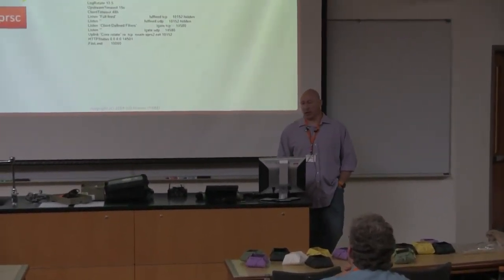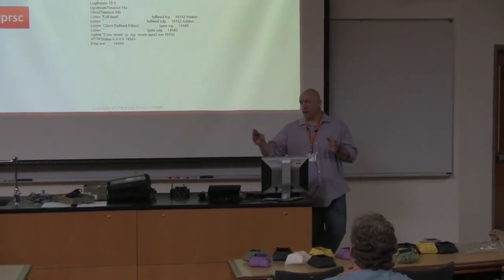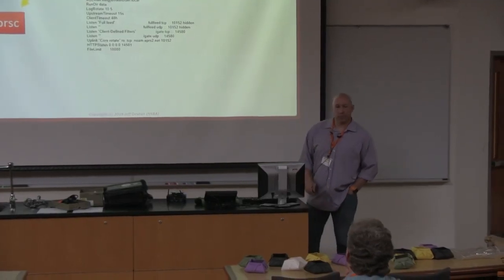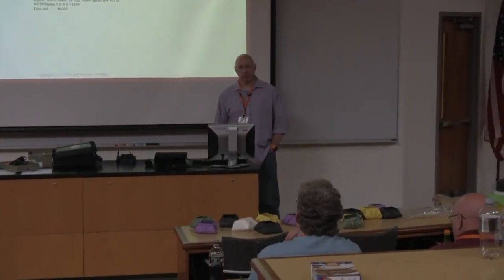Yeah, Jeff's comment, for those online, was that RTL FM will scan those frequencies. It doesn't do it in parallel. You might also point out that Direwolf does need a tweak for the multiple channels coming in. Yes, out of the box it doesn't do that. It's limited to 2 or 3 channels. Yeah, by default, Direwolf out of the box, unless you compile it yourself and make a change to the source, will only be set up to listen to 3 channels, because who would be dumb enough to want to listen to 6 or anything like that at once?